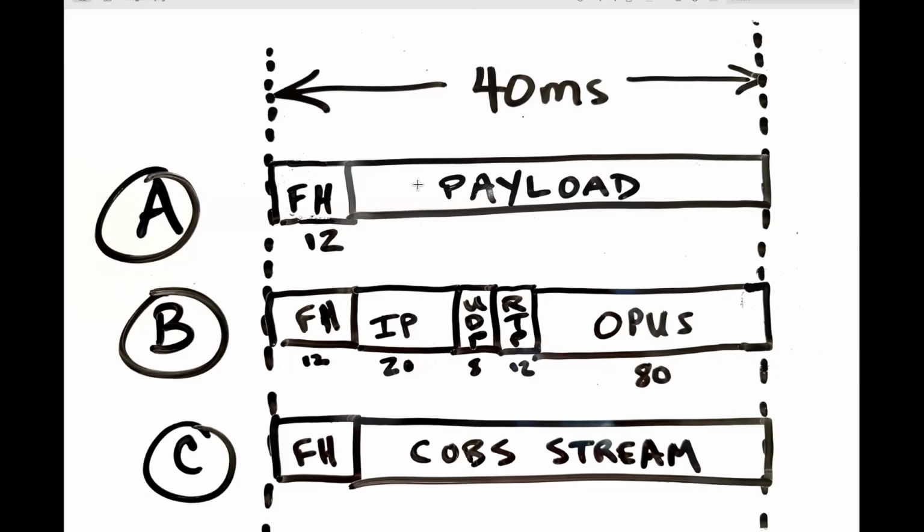And what we designed here is a stream of packets, which are considered to be all interchangeable at a certain level. And then the coolest way that we could find to delineate the packet boundaries is something called COBS, which stands for consistent overhead byte stuffing.